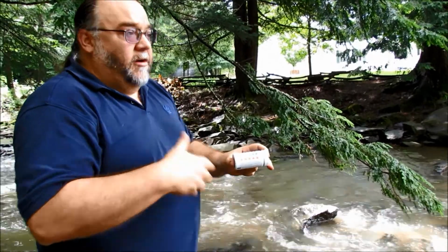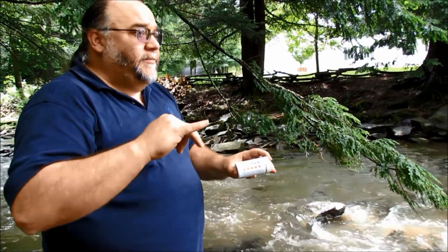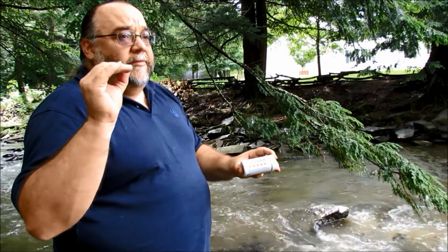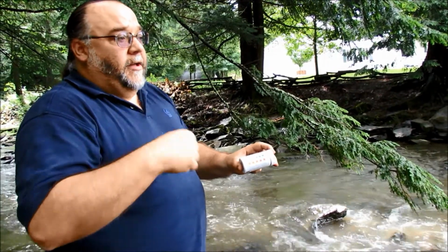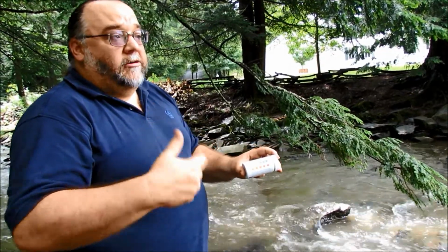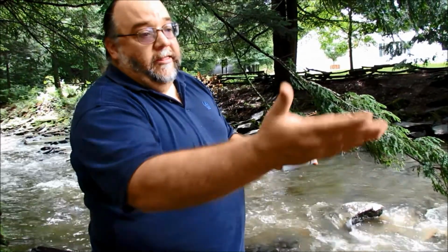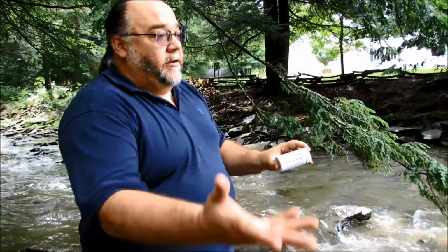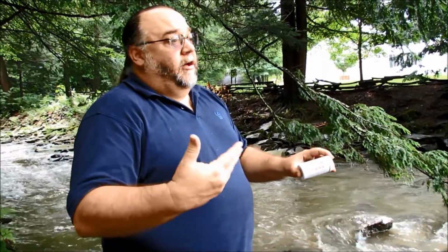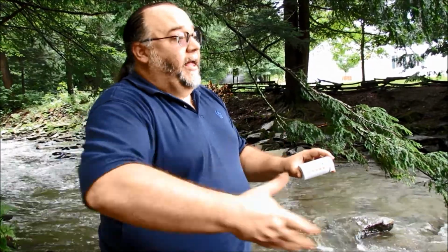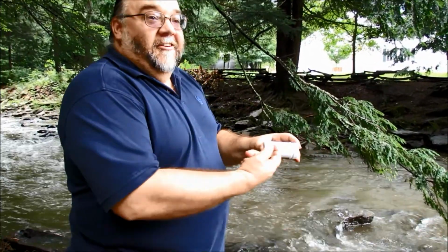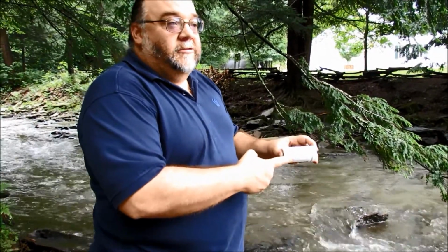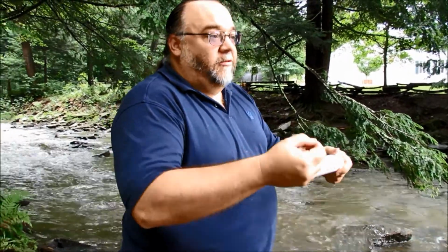Hardness around here tends to be low, but there is some interbedded calcareous material. What we sometimes do to manage alkalinity in waters is add carbonate. If you ever put riprap in here to stabilize this, you would go with a dolomite or a limestone, because it adds buffering capacity and helps stabilize it because it's eroding. And pH, if you can't afford a pH meter, you want to know if you're in a good range. All that's in one quick test.